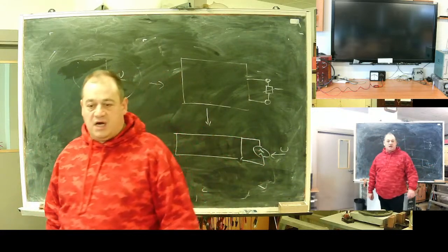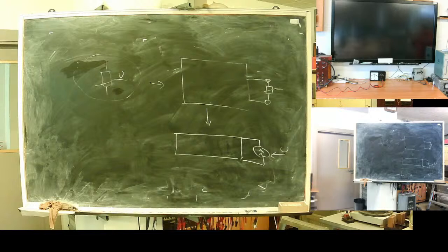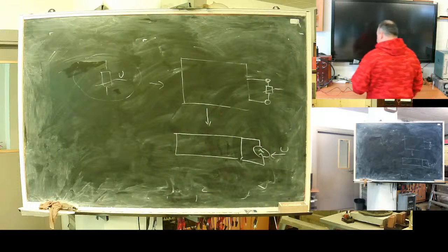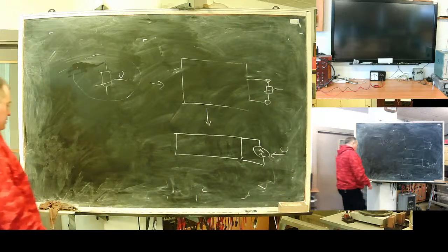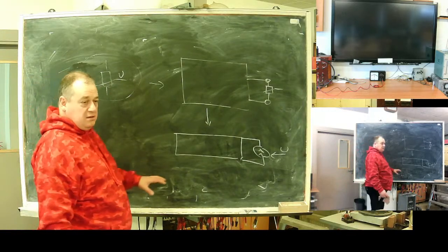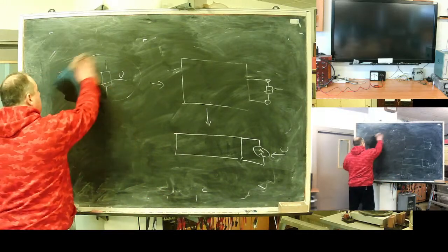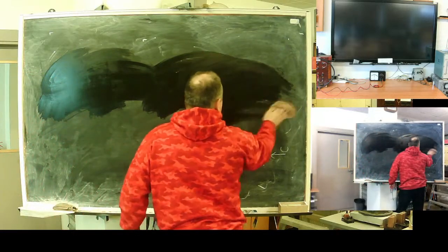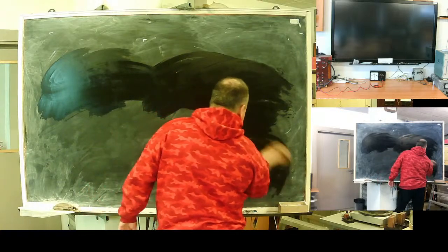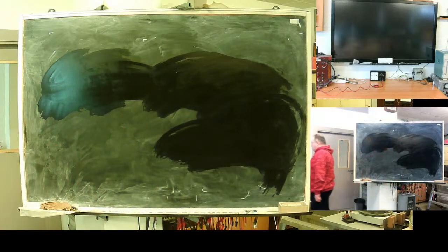So separate into linear and nonlinear parts. The core network represented in symmetrical components should be linear, and the nonlinear element should be separated and represented as a controlled resistance or, my suggestion, a controlled current source. It works better from the viewpoint of feasibility. Okay, let's go forward.